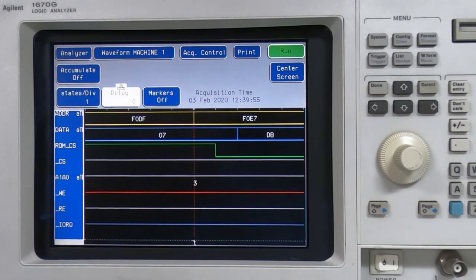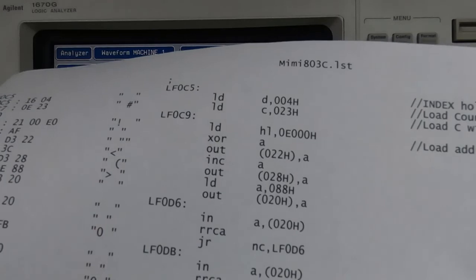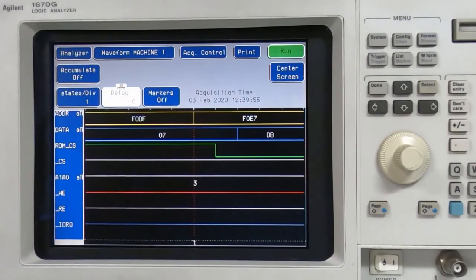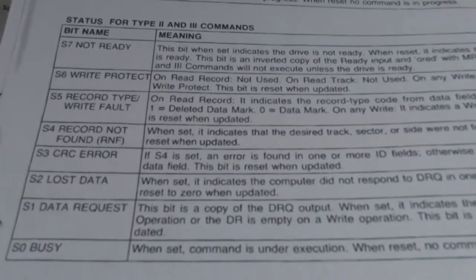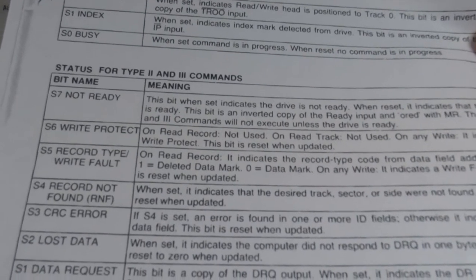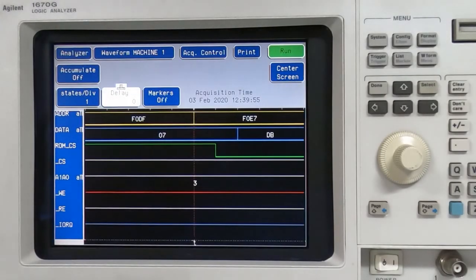But what I'm really trying to show in this video is this is a very good and powerful fault finding technique. If I wasn't videoing this and talking, this would have taken probably 5 or 10 minutes. And you can see that we've gone right through, tested all the functions within the operation of the floppy drive controller chip. We know why it's failing, we know what particular flags within the device are being set or are not being set, and we know that no data is being sliced and put into the data register. So it gives us a lot of information.